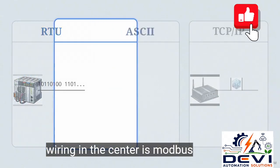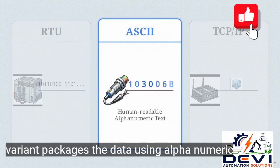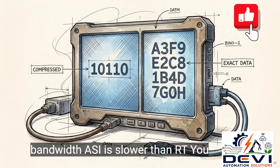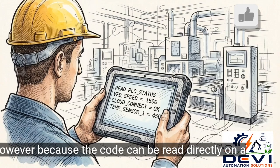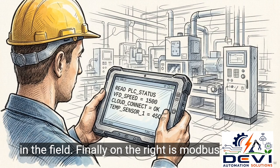In the center is Modbus ASCII. Instead of compressed binary, this variant packages the data using alphanumeric text characters. Because text requires more bandwidth, ASCII is slower than RTU. However, because the code can be read directly on a screen without a translator, it simplifies troubleshooting in the field.